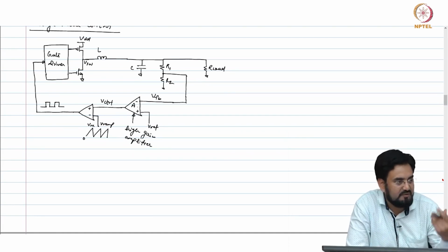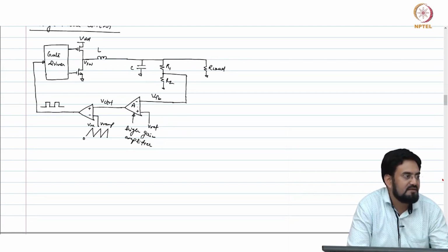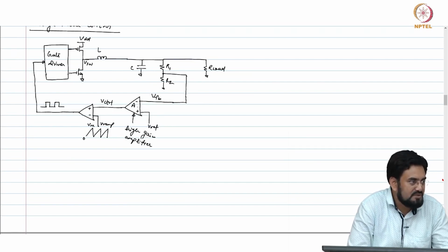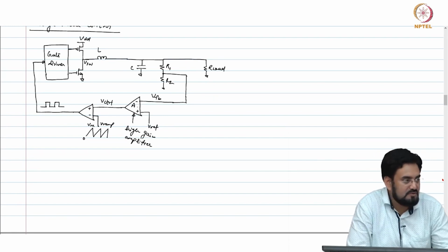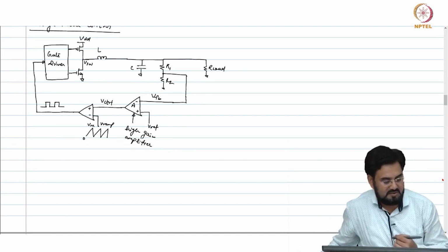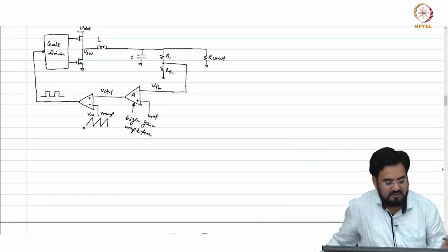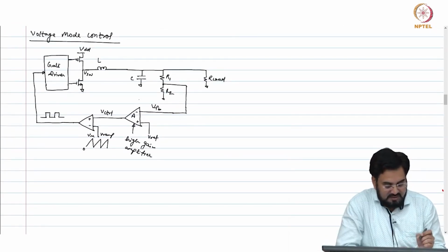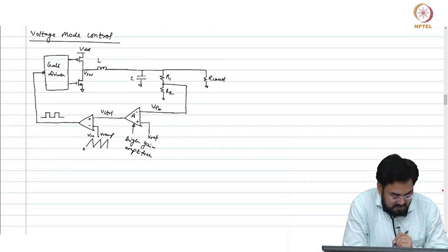If you make the gain 40 dB or so, 100, then that error will increase, and we already talked about these sources of error in LDO, if you remember. So DC gain was one of the factors, because you are in the closed loop, it is A over 1 plus A beta. So if A is very high, only then you get 1 over beta, otherwise A will also come into the picture and it will cause error in the output. So that is why we need a very high DC gain for any regulator actually, irrespective of whether it is switching or linear. So in order to meet that requirement, your A should be very high.